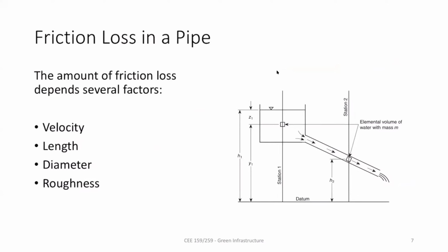And one of the things that you have to think of is friction loss in pipe. So let's think of conceptually first how friction loss is related to these parameters. Friction loss means when the water moves here, this is the velocity. I'm asking about the friction that is caused here because there is no friction beforehand. Friction can also occur because water molecules are rubbing against other water molecules, but mostly it's because of the pipe, the side of the wall. So if I ask you, if velocity increases, does friction decrease or increase? Because this is going to be a quiz question in the next quiz.